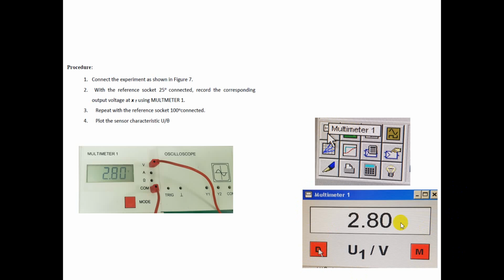You can change the view, how to view this one, by changing the value of D. Okay, so this is 2.0 volts. Similarly, M means you are changing the mode, either you are looking for the current here, so then you can change from M. Right now we are using the voltage here, so that's why we have V here. Similarly, for resistor, you can change from here to view the required resistance. Okay. Next thing is,